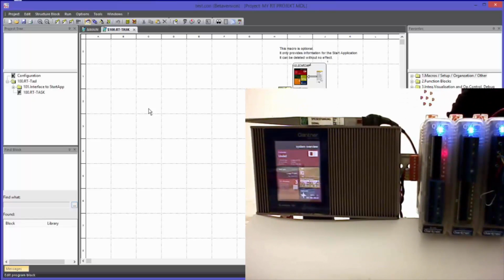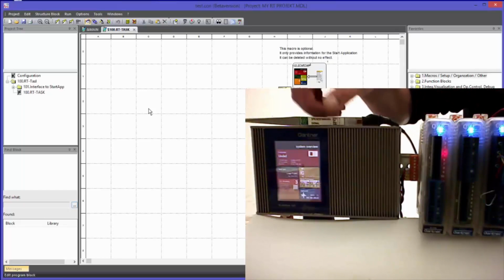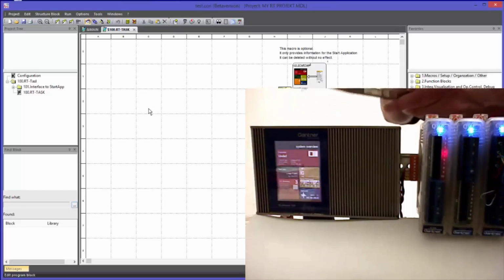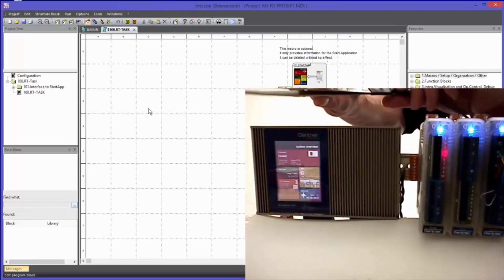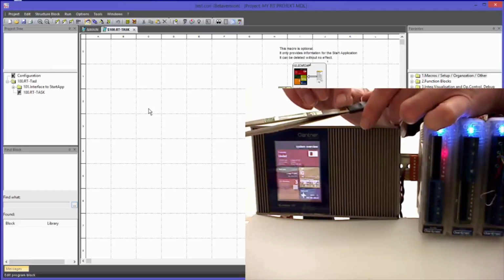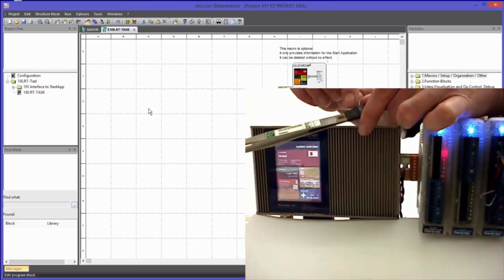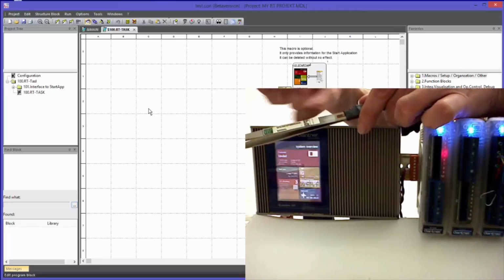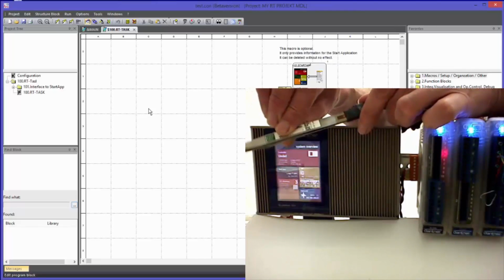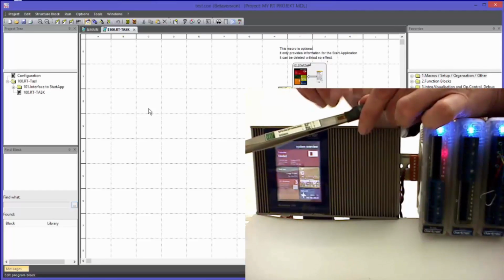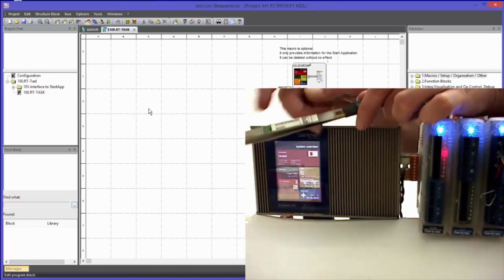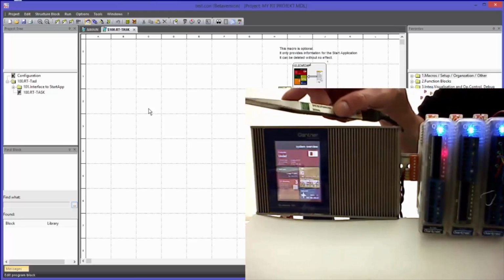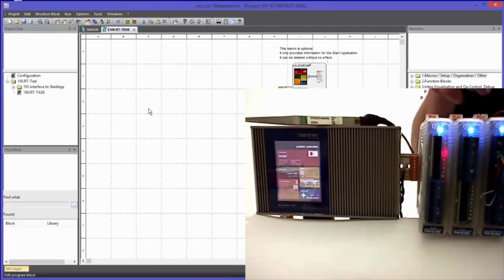On the webcam screen down right, you can see a Q.station with Q.blocks modules. Furthermore, you can see tweezers with an attached strain gauge. The strain gauge changes its resistance when the tweezers are pressed. The resistance change is transformed over the bridge circuit into a voltage change. This voltage change is measured in the A101 module and can be accessed in the application accordingly.